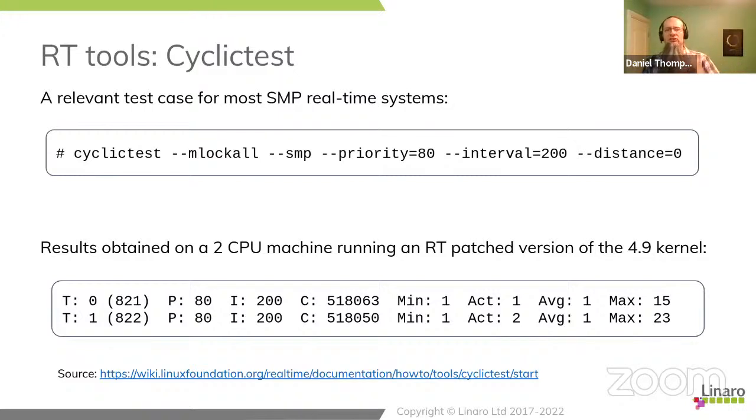So because cyclictest can also observe firmware related costs like the wake up time, it does give you a very good full system view. And like I say, it has in the past been used to say, well, this PC can't be used for real-time systems because its firmware is not adequate. And then you go and get a different PC. In the ARM world, I rather hope that its embedded centric nature means that there'll be more pressure to get the firmware fixed and so on.